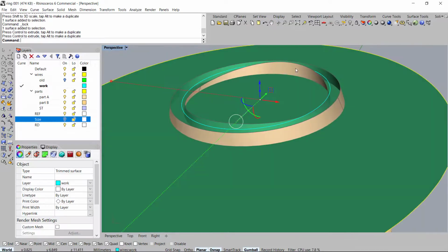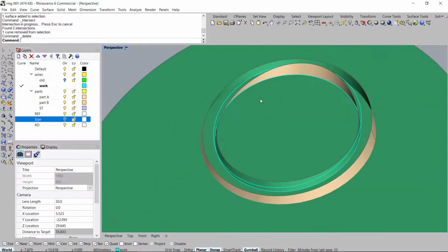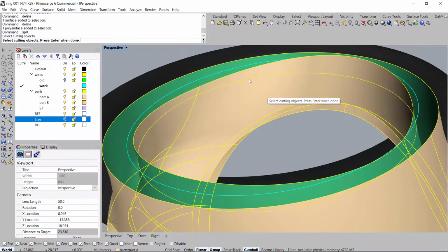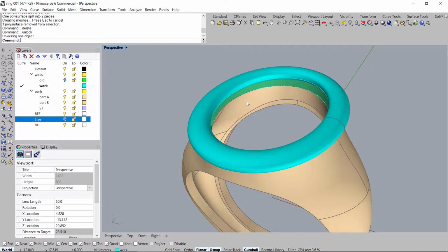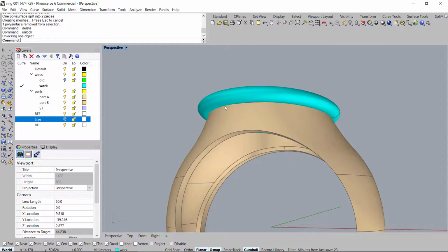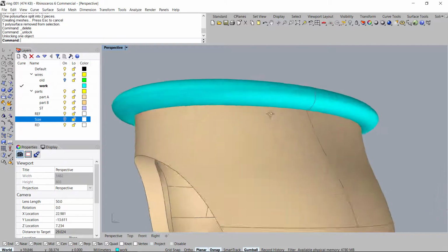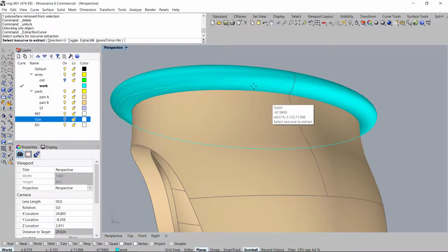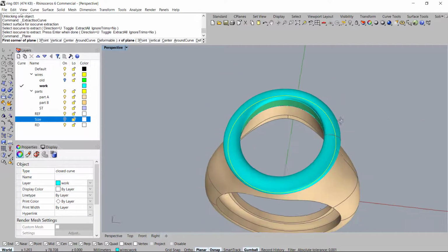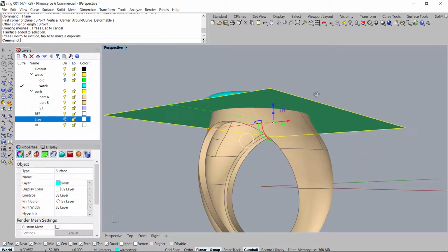Okay, so select the body, plane, intersect. Just keep this curve, that will be our cutting curve. Delete the plane. Let's go ahead and just split that with that inner cutter curve. Bring everything else back. I do want to transition this to the shank because I'm not feeling this weirdness to it, you know, it doesn't look very attractive. Again, we're building this from scratch, so we don't really have any direction. It's mainly to show you basic techniques of building complex surfaces. You know, I'll be doing a series of these as I go in future videos.